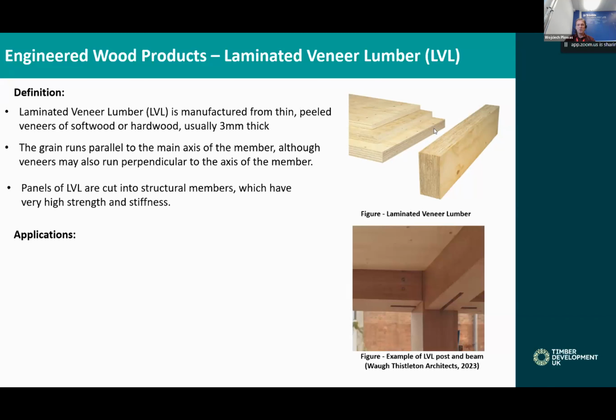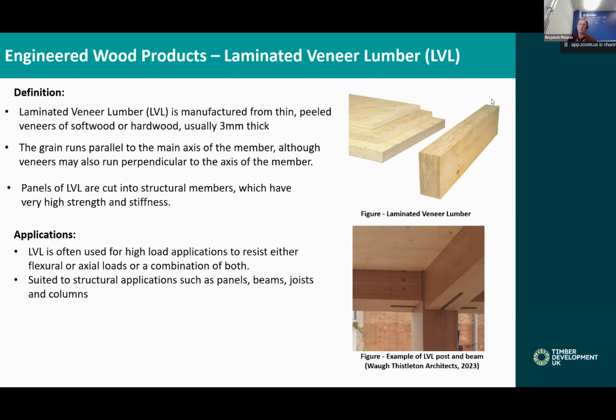And that kind of leads me to the applications. LVL is very strong compared to the previous products I've described. So you would probably want to use LVL in applications where higher strength is required, because it can resist much greater flexural or axial loads, or a combination of both. It's suited for structural applications such as panels, beams, joists, and columns.